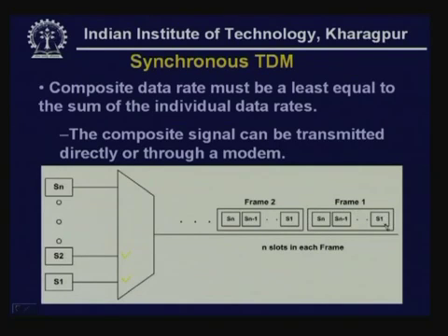As you can see here, in this frame, first we have got the data from source S1, then from source S2, then source S3 and so on up to Sn. After taking data from n sources, again it starts from source S1, as you can see here, the second frame is started, and then from source S2, then from S3 and so on. Then this is sent in terms of time. So, this frame is sent, then this frame is sent, and so on.